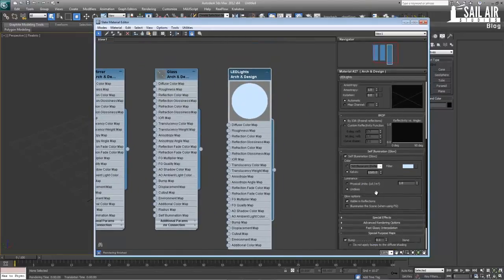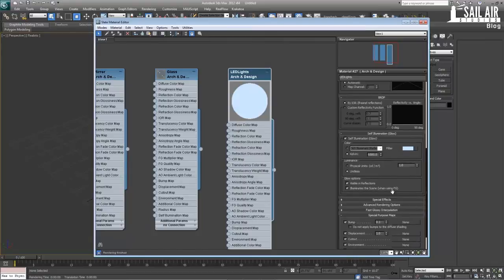However, we do need to make sure that it illuminates the scene when using Final Gather. So what this does, right there, defines if the self-illumination effect is actually illuminating the scene with Final Gather. Final Gather sends out light particles, I guess, and then from there it determines how light an area is. Since we want the inside of the box to be light because there's light all around it, we will use these for final gathering. So that will be that.